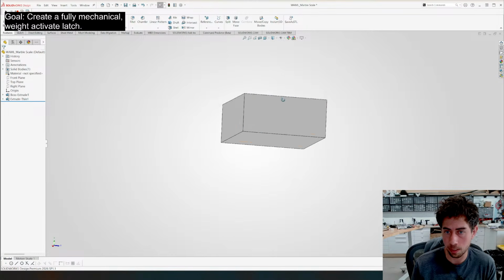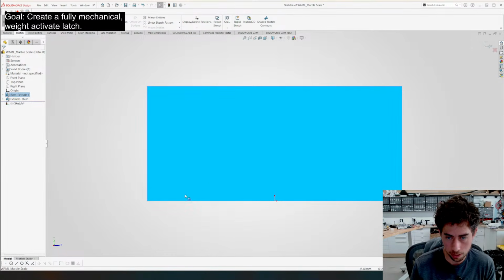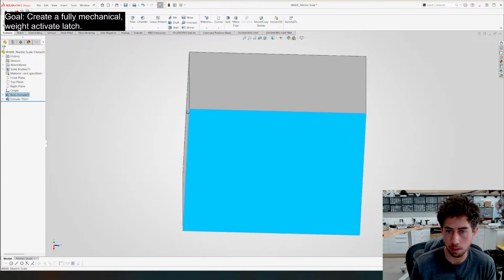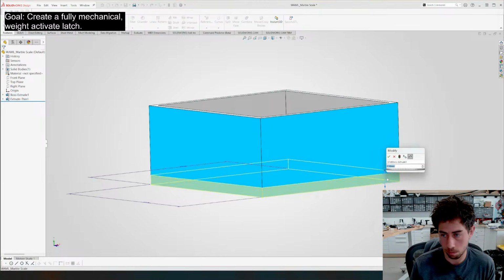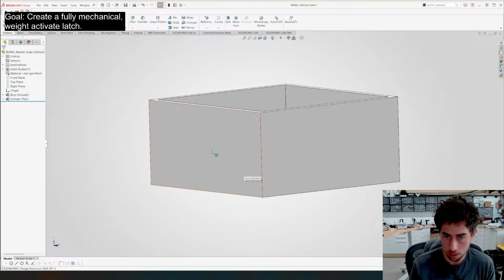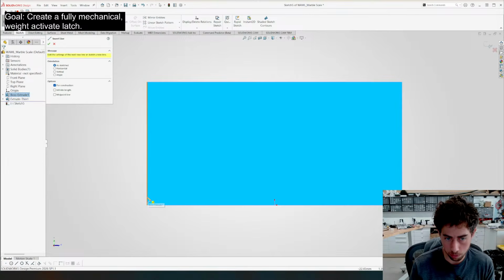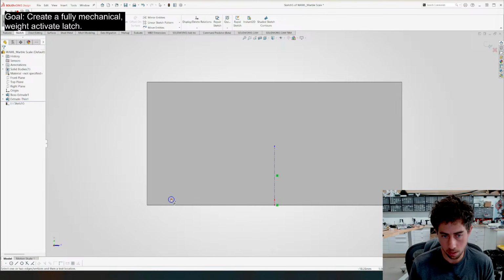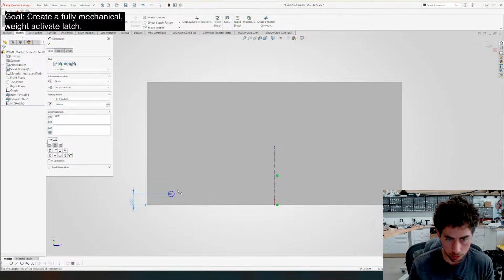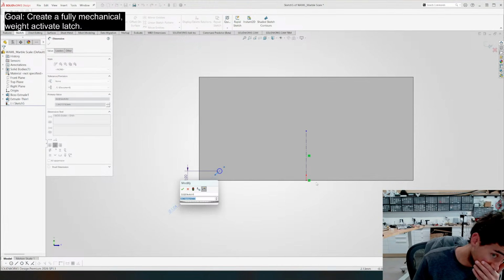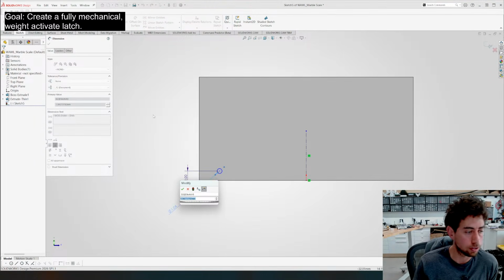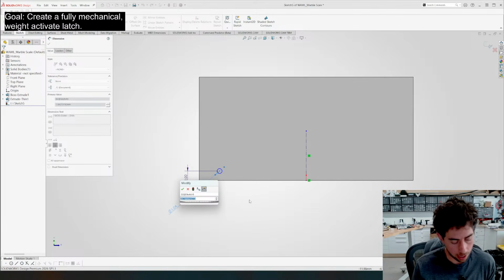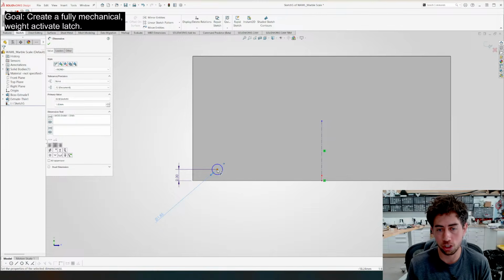And I need to be able to put some screws on the side of this. So I'm actually going to make this a little bit thicker at the bottom. It's 2.5. I'll make it 4. And we're going to put a couple screws in the middle there. I'm going to be using probably number 2 self-threading screws. So that's why I'm going to make this whole dimension like 1.85, and that should work.